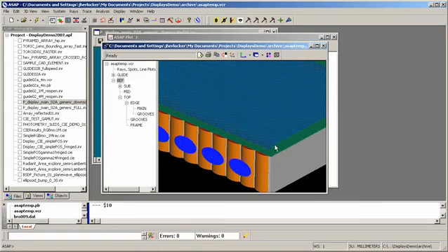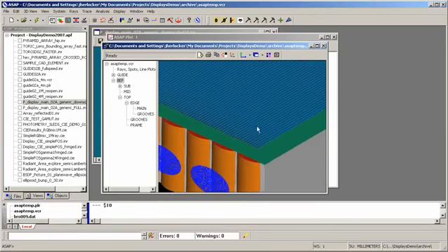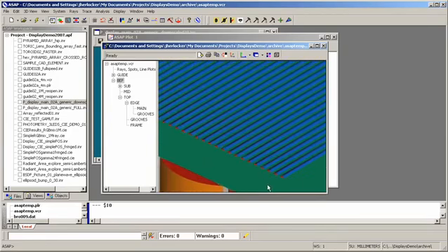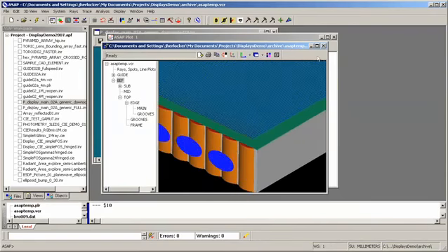And then, we'll really have to zoom in to see these well, we have little ridges that stand up above the surface, and these little ridges are cylindrical ridges which cause the light to cross-couple. Instead of having the light from each LED just plunge forward along the guide towards the other end, when we impinge on the top surface and we see these little ribs, it causes the light to be diverted to the side. And when we do a ray trace, you'll see some of that action.